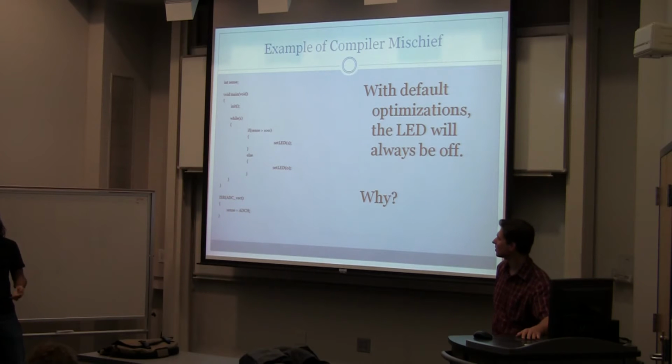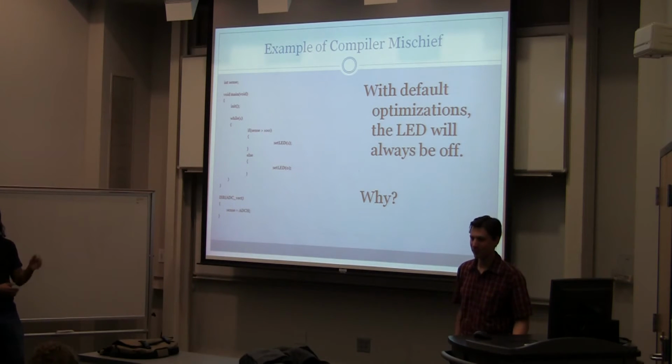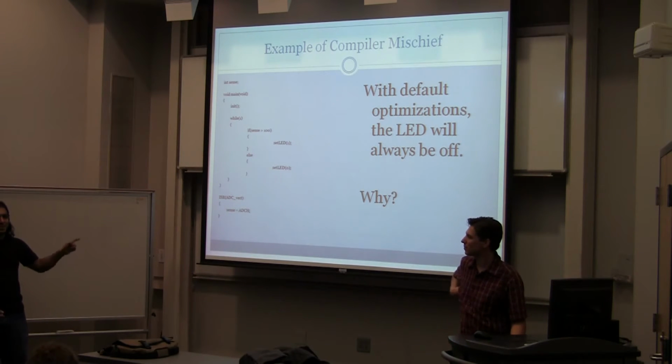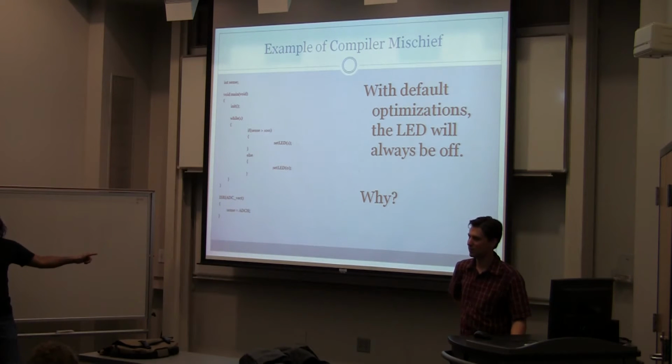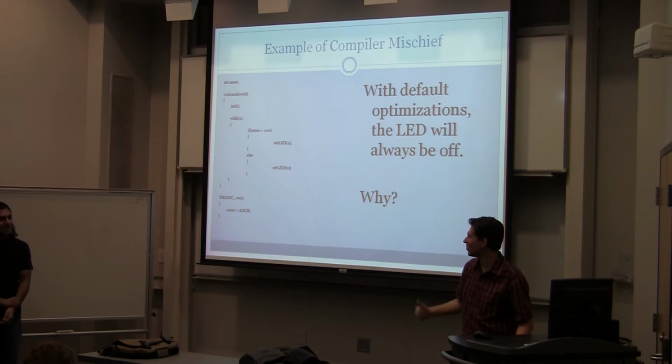And the volatile keyword, in this particular case, is telling the compiler, what I want is for this variable to possibly change from multiple places. So treat it as something which is volatile, which you're not sure about. Don't be so sure that it will not change. Exactly.